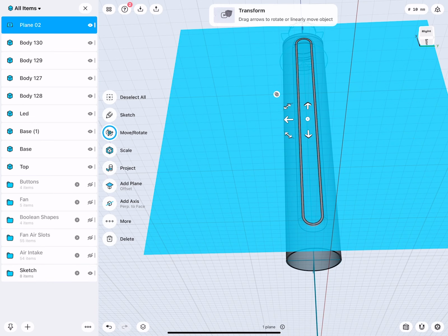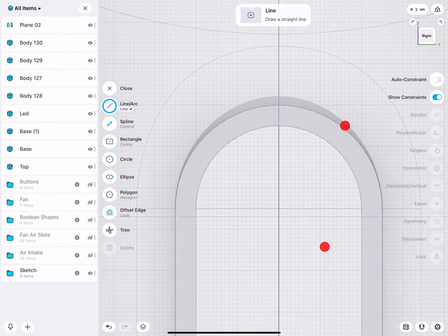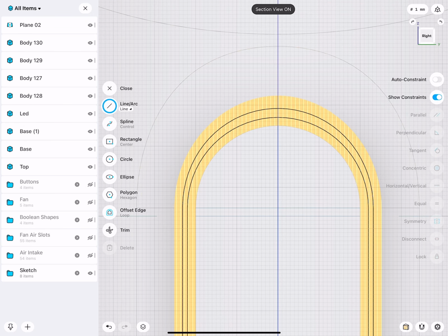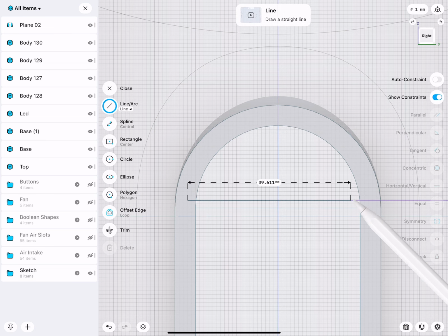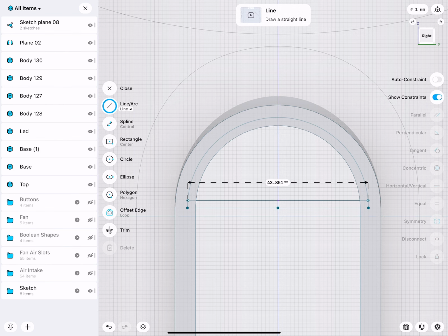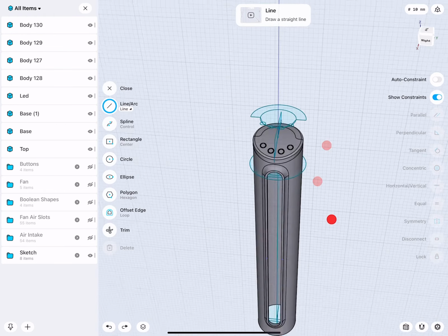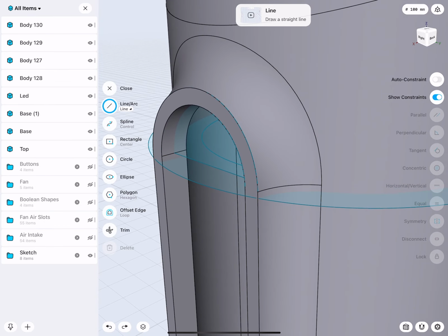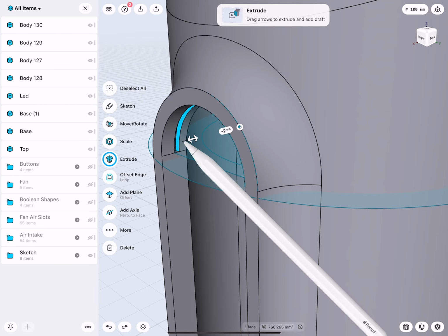Then I can select the face with the finger double tap. Then I go on to that construction plane. This construction plane slices through this design. And now I can create a sketch that is a little bit bigger than the interior opening. So let me undo these steps because it's a little bit bigger. There, I can now go ahead and